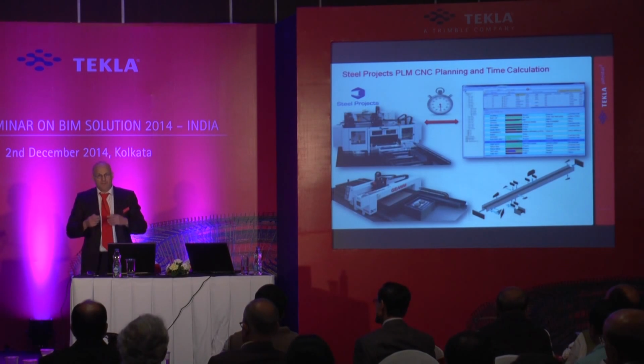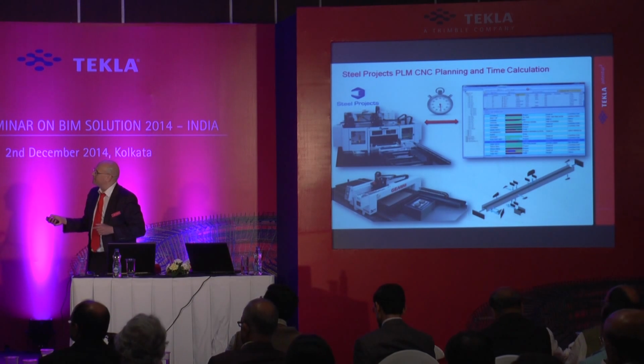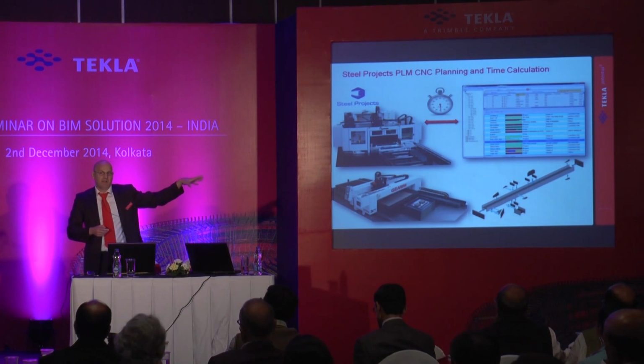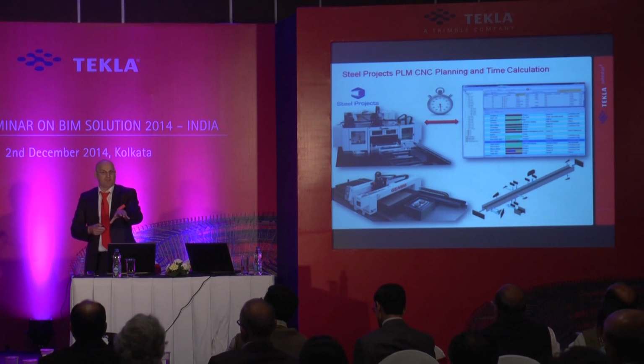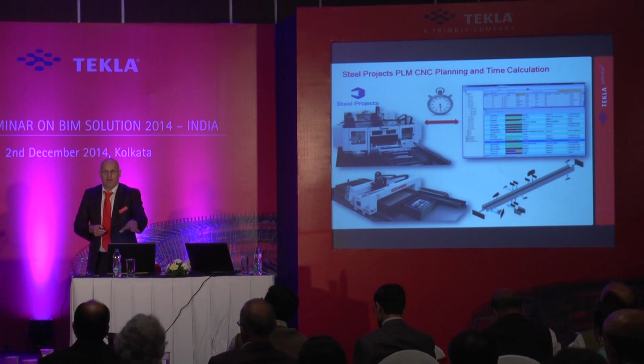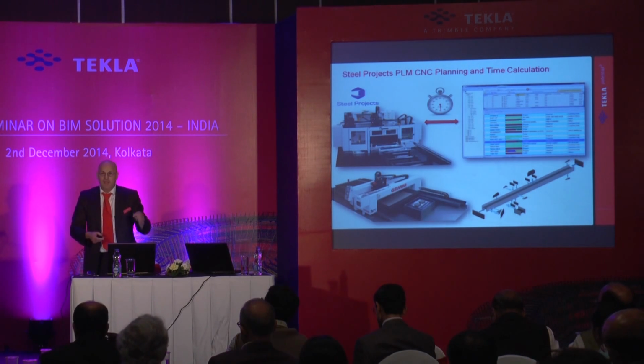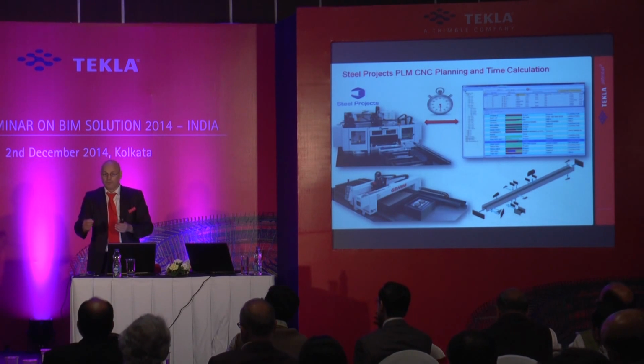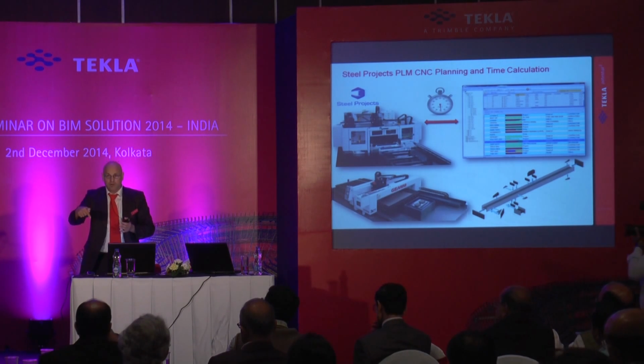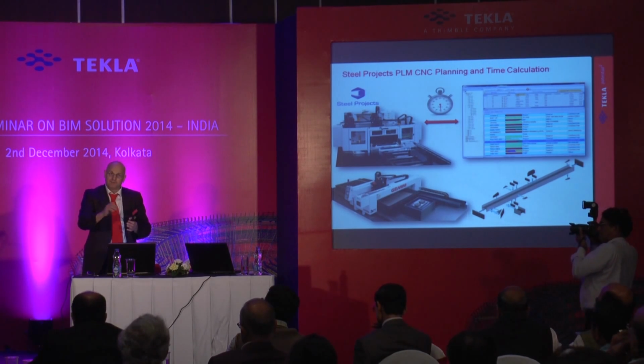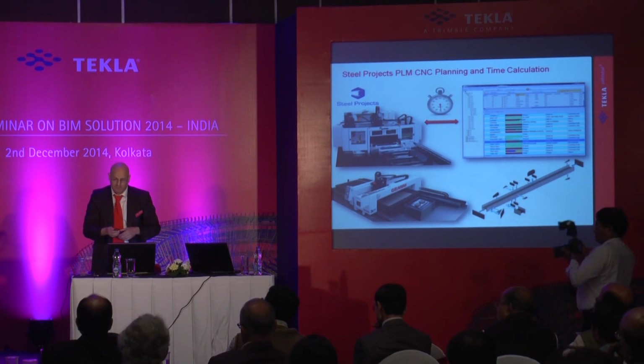Once it's within, the higher level software can then do a time calculation. It looks at all the pieces from Tekla and says, oh, it's going to take my factory 4 days, 4 hours, and 5 minutes to make these pieces. And if a machine is, let's say, out of commission, it will then take 5 days. So it will actually recalculate it for you. And that's based on actual holes, so it knows a 22 diameter hole takes longer to drill than an 18 diameter hole. So even down to milliseconds, it calculates it for you.